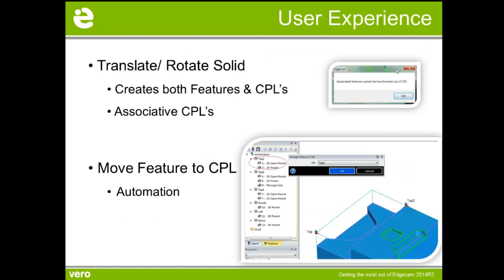Having created a CPL, we know a CPL sticks to a solid model, and you'll appreciate that if you were to move a solid model, the CPL would have stayed where it was. Now you'll notice that the CPL is associative. It will go with the solid model, whether you rotate or translate it. More so, if you copy the solid model, it's very usual to say, I'm going to do a multi-load, give me 5 copies in the x-axis of this solid model. Edgecam will recreate and copy the CPL at the same time. So a lot of legwork has been removed by that one enhancement.